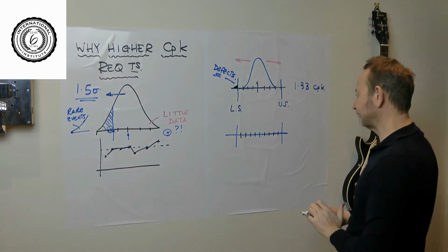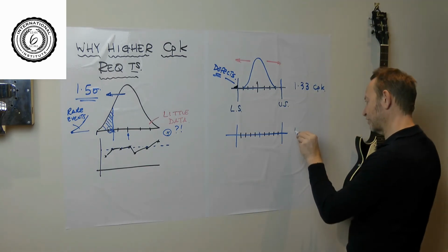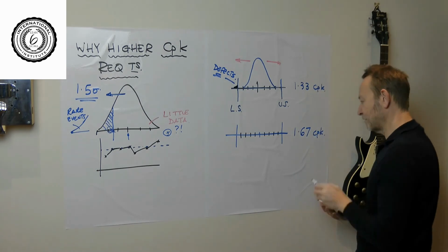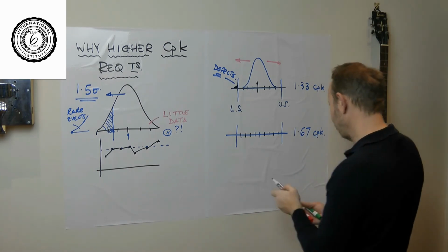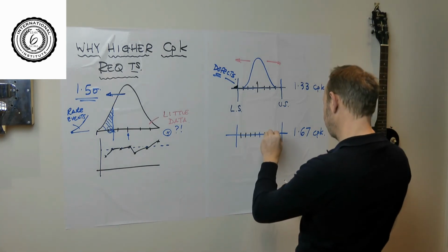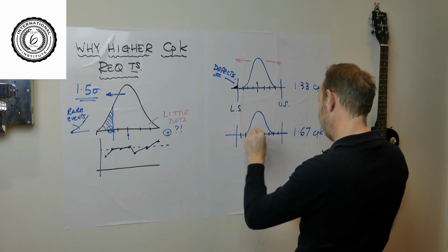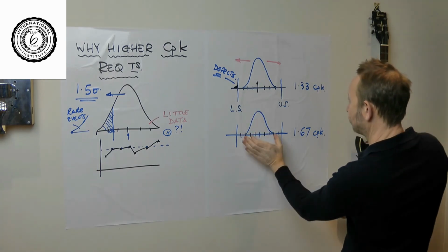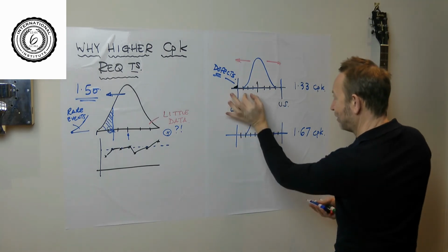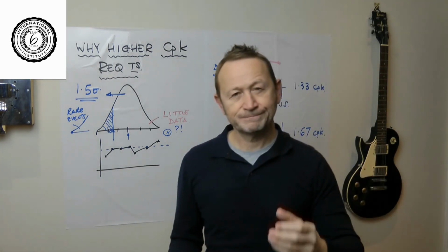There's 5. Now this is a 1.67 CPK. So now we draw in the normal distribution. So we keep the colours the same. We draw in the new normal distribution. Okay, now you can see it's slightly smaller. The sigma is smaller as well because it's about 25% smaller.